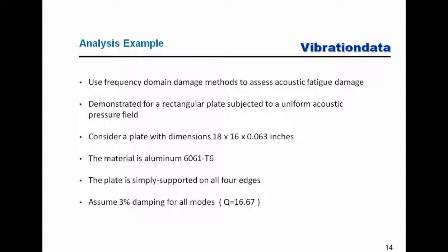We're going to assume that it's simply supported on all four edges. We're also going to assume 3% damping for all the modes. And 3% damping for all the modes means that the Q value is going to be 16.67.